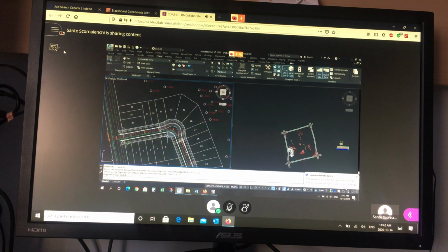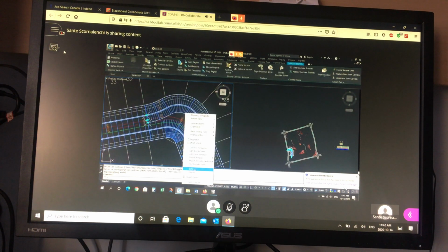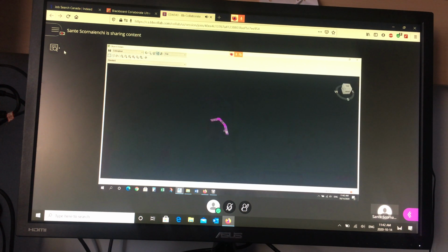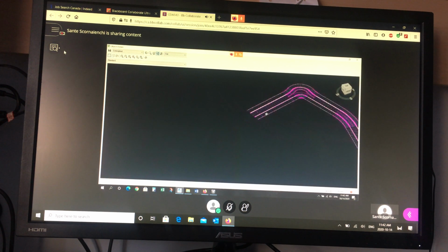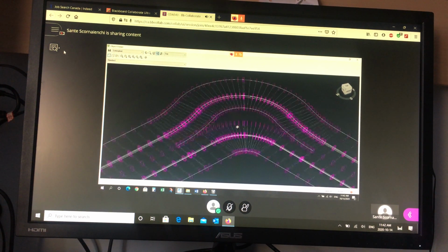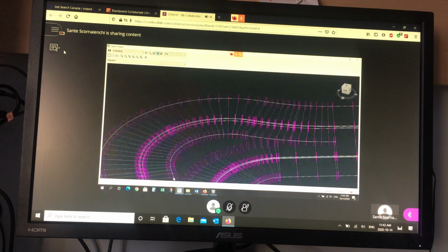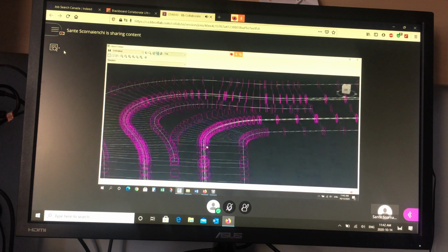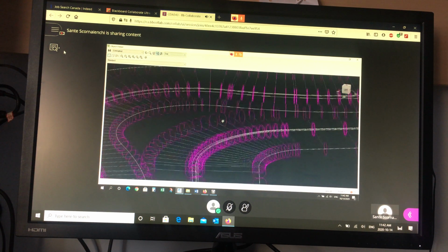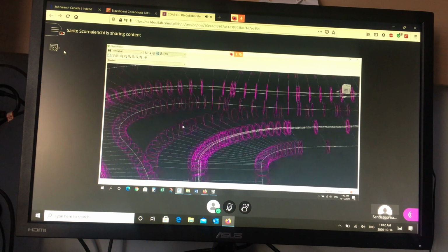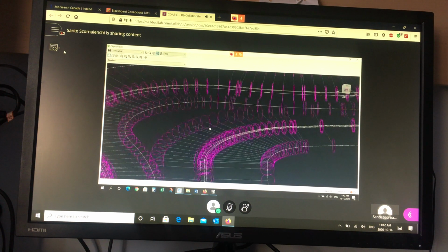In this case now I'm going to show in 3D. So I'm going to go to Object Viewer, and I'm going to tilt this so that we can see what's happening here. I want to go down kind of the barrel here so that you can see the effects. Here's the center line of the road where there's no white line, and here's that edge that's in the wrong spot. I want this pavement to get longer. I want it to match the center position, and then I want it to match vertically as well, because what's happening on the center line is correct. So I just want to show this to you.